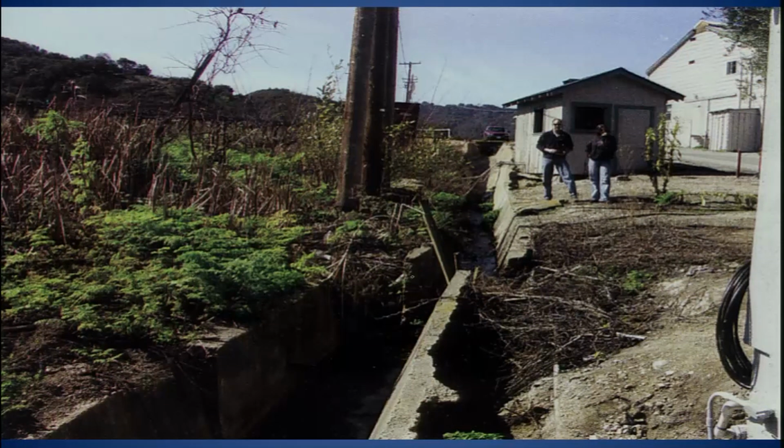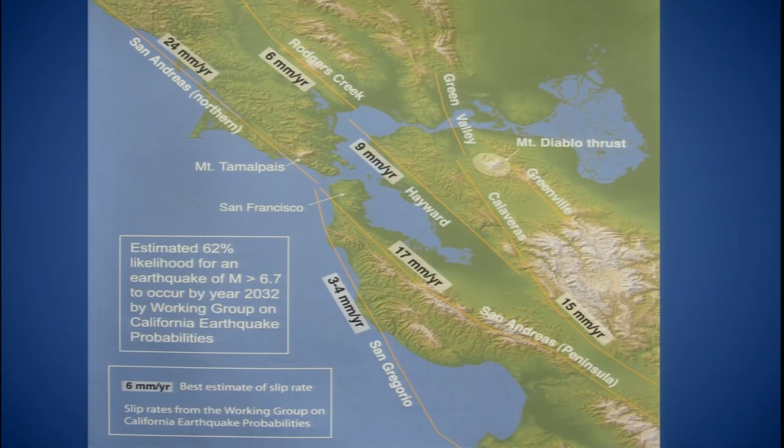So this is an example of the Hayward fault, which shows creeping here. So this portion has moved here, and this one is over here. So the fault runs somewhere here. So this portion is your typical right lateral. If you stand here and view, or you stand here and view, then it will be the same motion. So you have right lateral strike slip faulting along this fault.